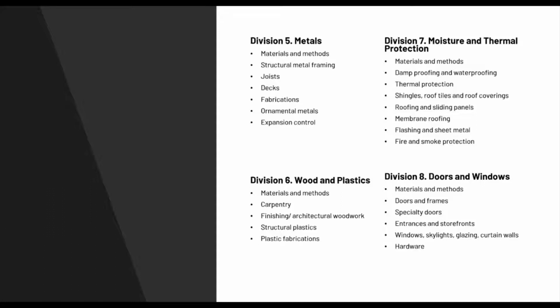Moving on, Division 8, this is what I was saying kanina, doors and windows. There's a specific division for your doors and windows in terms of specifications. So, Division 8 would include that, your doors and frames, specialty doors, entrances and storefronts. If you have windows, skylights, glazing, and curtain walls in your project, include that in this division also. And of course, the hardware, yung mga hinges nyo, for a doorknob sa division na ito po papasok.